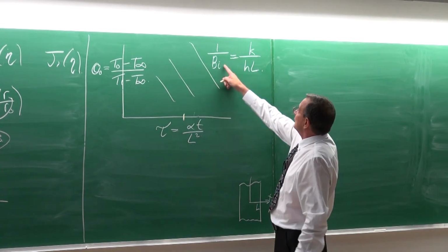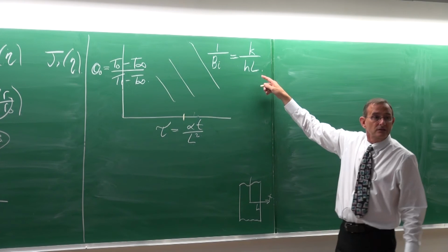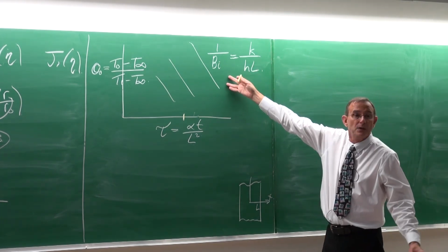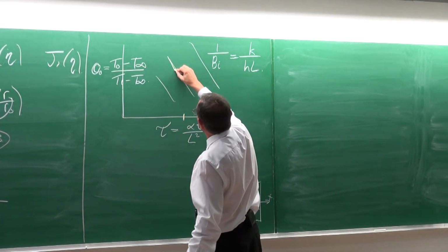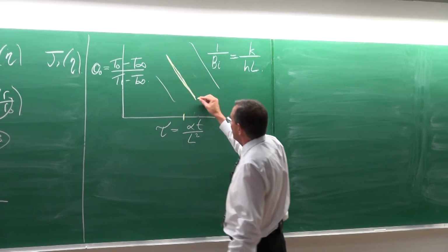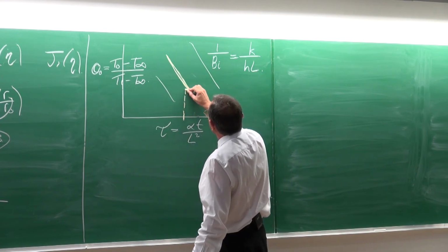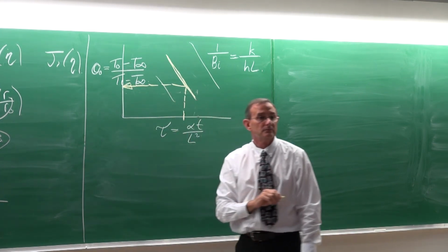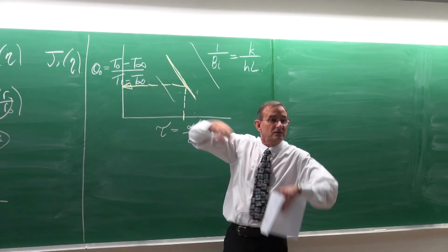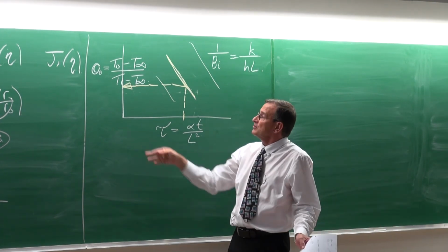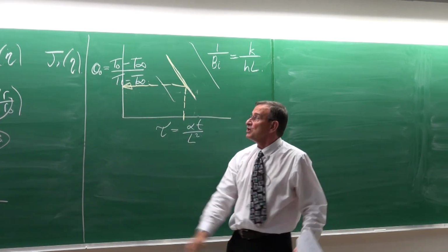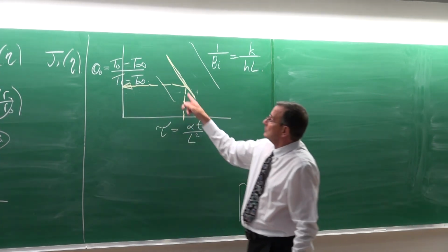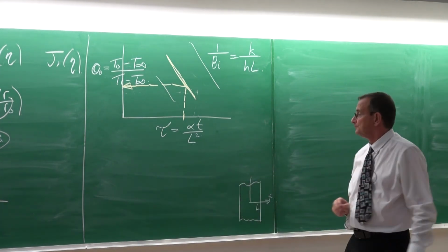Again, if you've got the properties of the body, the k value, its dimension, and the heat transfer coefficient, you can calculate the Biot number. So you can get the relevant line there. Let's suppose it is that line there. So then it is very easy. You would go up there, and there you will find the solution. Okay. T infinity is the temperature on the outside. Ti is the initial temperature. T0, the temperature at the center. So you can get it from there.